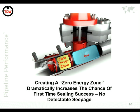So you drill again for the bleed valve? Yes, all of these have small holes, small hot taps in there. You've got to remember that when an operation like this goes on, there are a number of tappings going in at all times. You'll also see that there's a reinforcement clamp on there as well, and that often has to happen because the hoop stresses induced on the pipeline by a sealing plug are quite high, and you need to ensure that you can support them here.